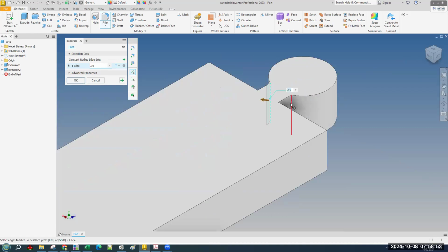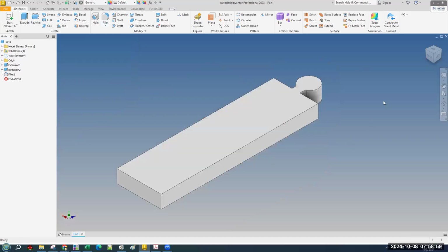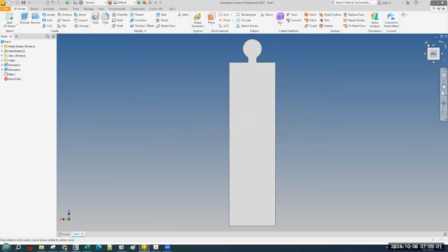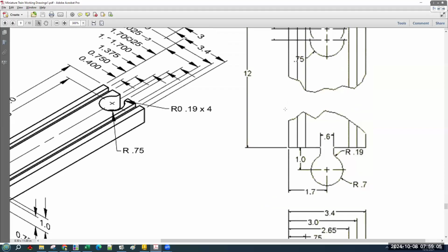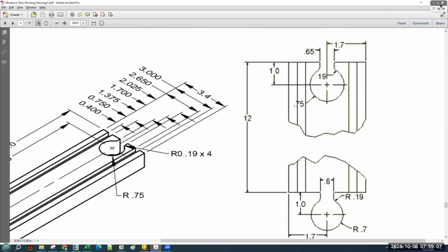And you can do this on the same part feature, meaning choose both of them because they're the same dimension. And that is one of the sides. The other side, or the other receiving side, is very similar. It's going to be a similar shape, except it's going to be drawn on top of the part so that we can cut extrude. And similar dimensions. We've got the same rounded over fillet, which we'll do last.